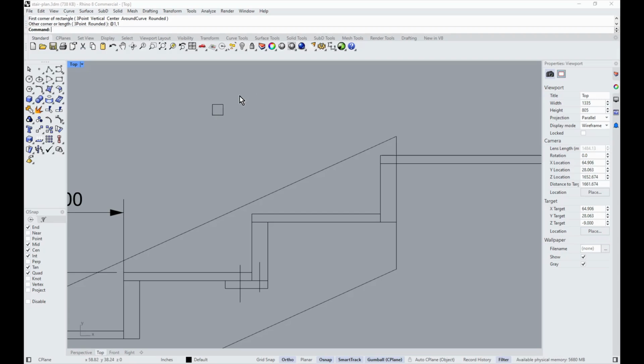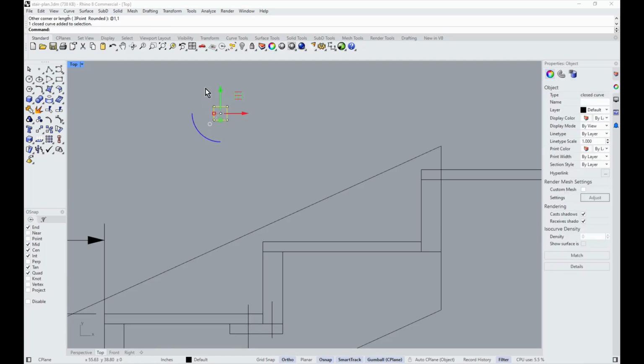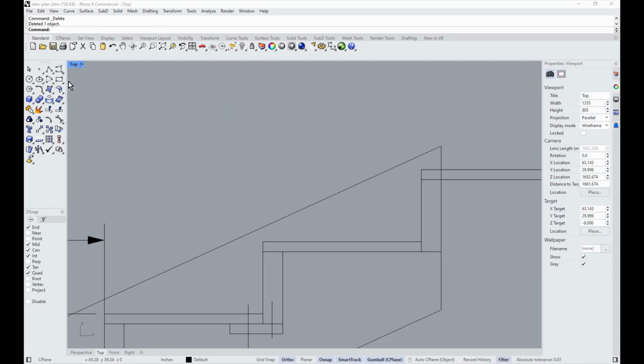Let's say you're going to get, actually, it'd probably be something like a 2x2 that's been ripped, or a 2x2 that has rounded edges on it. So relative at 1.5 comma 1.5. So there's all this, and then we're going to throw a radius on it of 3/4 of an inch, or sorry, 3/8 of an inch. So you took the fraction, turned it into the decimal.